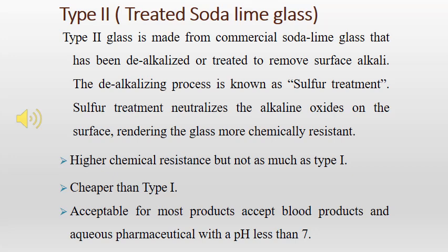It is made from commercial soda lime glass that has been dealkalized or treated to remove surface alkali. The dealkalizing process is known as sulfur treatment. This neutralizes the alkaline oxides on the surface, rendering the glass more chemically resistant. It is acceptable for most products except blood products and aqueous products with a pH less than 7.